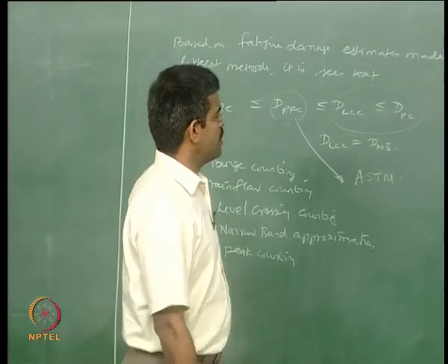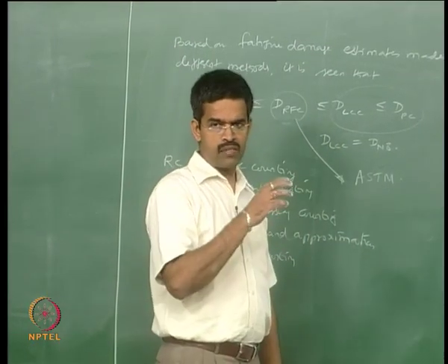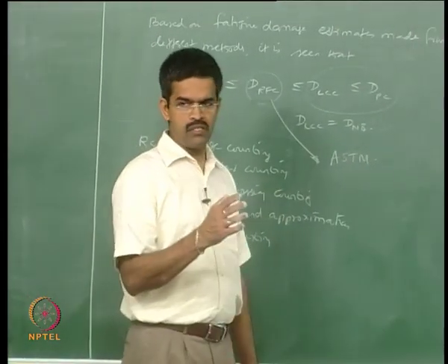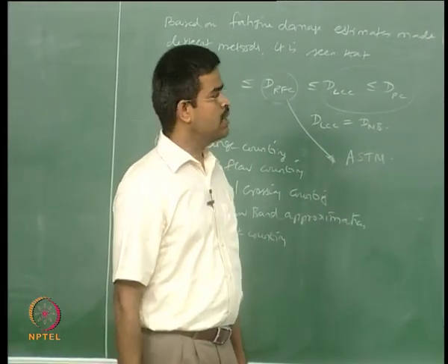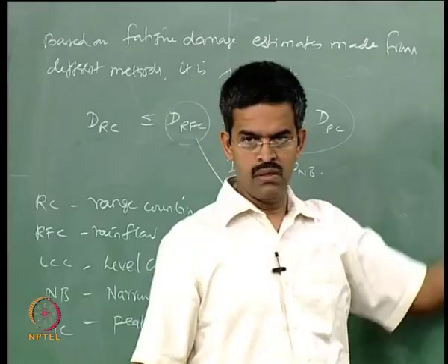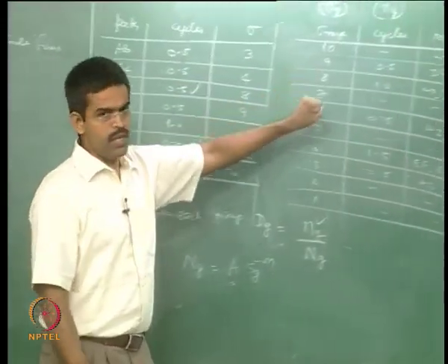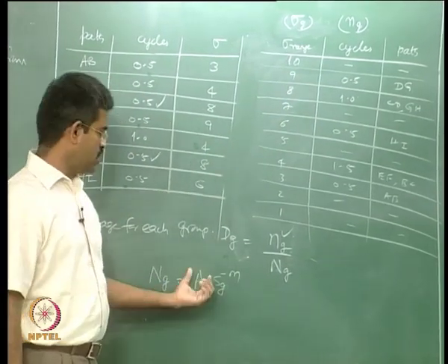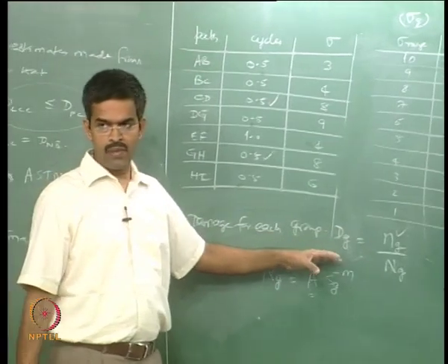So, if the time history is available, just turn the curve, make the axis of the time downwards positive, you get the stress range of peaks and valleys distributed to the right and left of a vertical line, identify the stress cycles, the stress ranges, group them, and if you know the corresponding Sn curve, then use this equation and find the damage on each group.